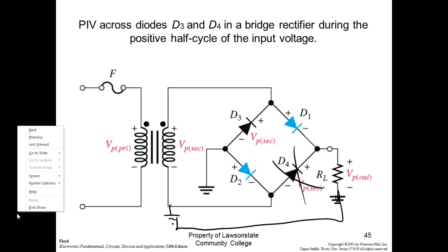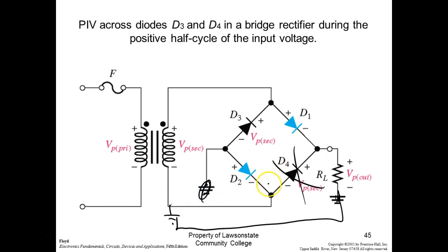Now what's neat about a bridge rectifier, let me disconnect this ground, is if I need a negative power supply, I just change my reference. So I'm going to just go over here and flip this around. So now this is my power lead. So here we got cathodes pointing, and this is the common, right? You understand? So all I did was change which way, so all you get off a bridge is a minus and a plus, right? You understand? So this is the minus because this is the cathode, this is the plus.